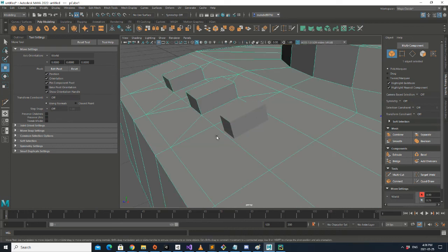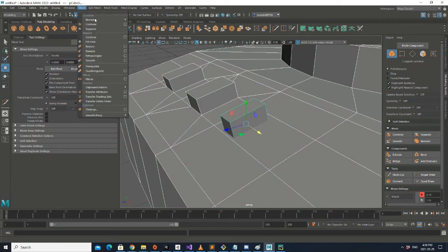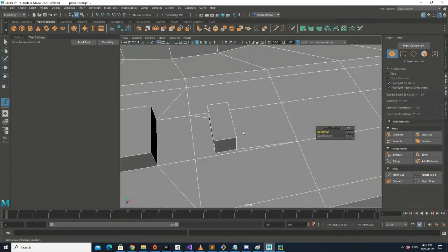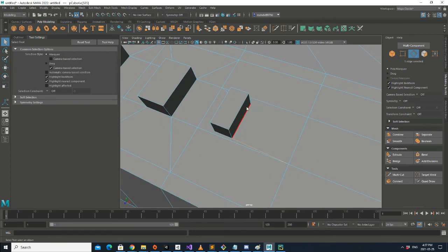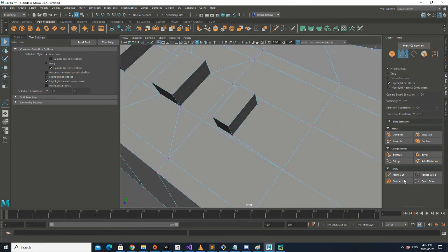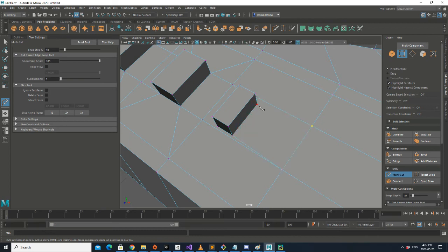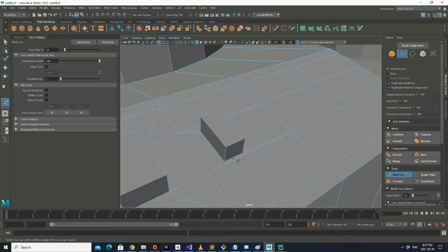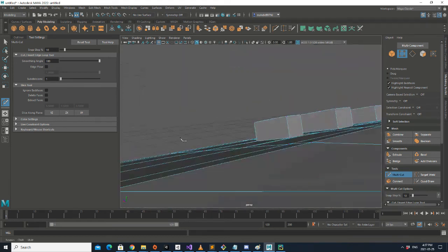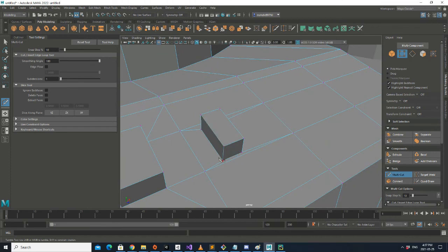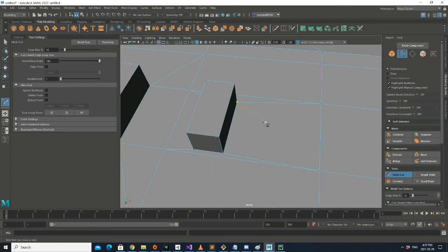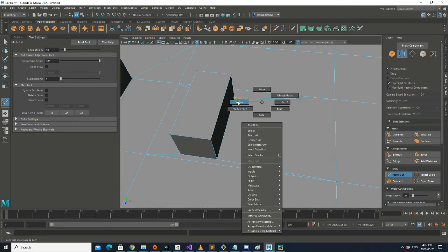And now what you can do is combine these 2 meshes with Boolean union, and then just delete. Oh yeah, that's fine. And then you can use the multicut again, add this one to this one. So for example, with having that, you will still have a face with 4 vertices there, 4 vertices there, and 4 vertices on the other side as well.